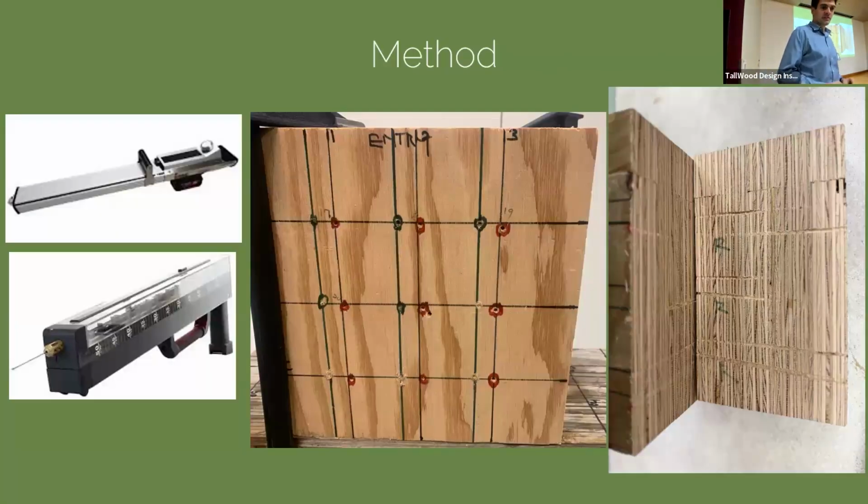So what we're doing, with a student working on this project, is taking two different tools, the IML Resi and the Rinntech resistograph, and taking these 8x8-inch test samples. We're starting with MPP because that's what we had available at the time, and essentially drilling a grid where both pieces of equipment drill in a grid pattern across these specimens. We're doing this with controls, delaminated samples, and then our variably decayed samples.